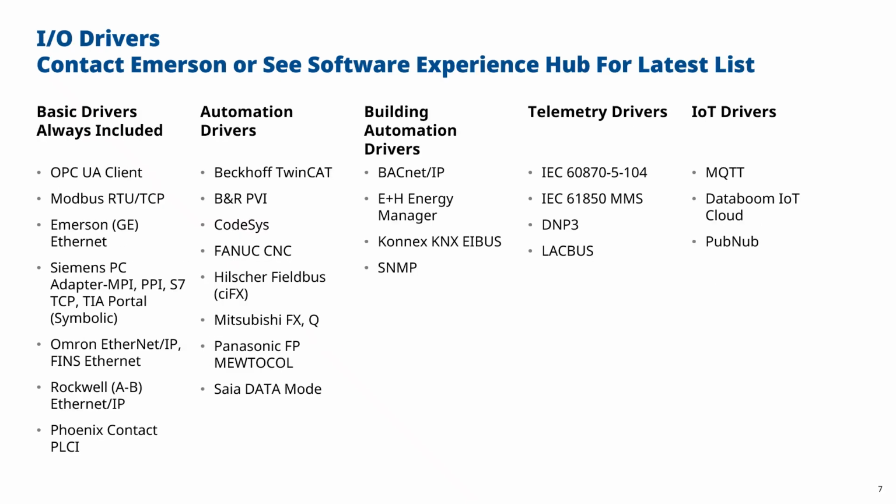Now, basic drivers are always included. So that includes OPC client, Modbus RTU and TCP, Emerson, what was GE, Ethernet, Siemens PC adapter MPI, PPI, S7 TCP and TIA Portal symbolic drivers, Omron Ethernet IP and FINS Ethernet, Rockwell or Allen Bradley Ethernet IP, and Phoenix Contact PLCnext. They're included as standard. To be sure of what you get, you can contact Emerson or see the Software Experience Hub for the latest